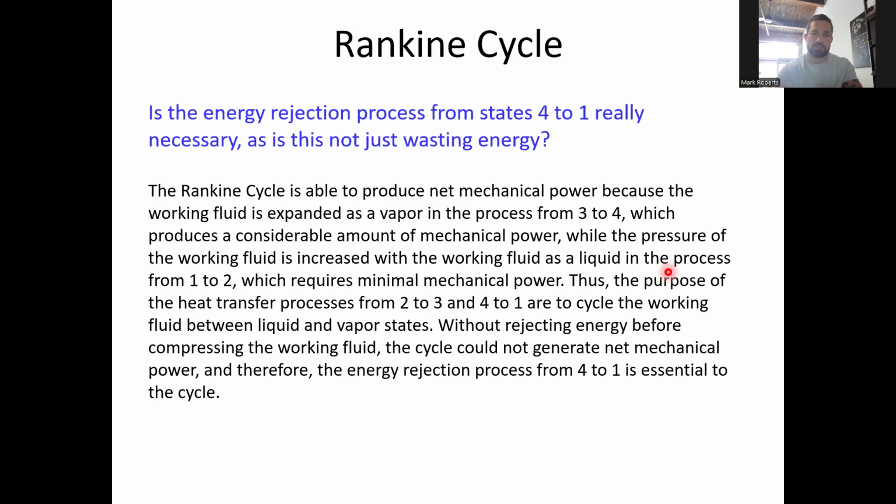All right, so this here says, do we really need to reject the energy from state 4 to state 1? Do we need to take that low temperature, low pressure steam and actually condense it? Yes, and that's because of what I talked about earlier: we can't generate net mechanical power without condensing to a liquid, because the amount of work required to increase the pressure of a liquid is significantly less than the amount of work required to increase the pressure of a saturated vapor.